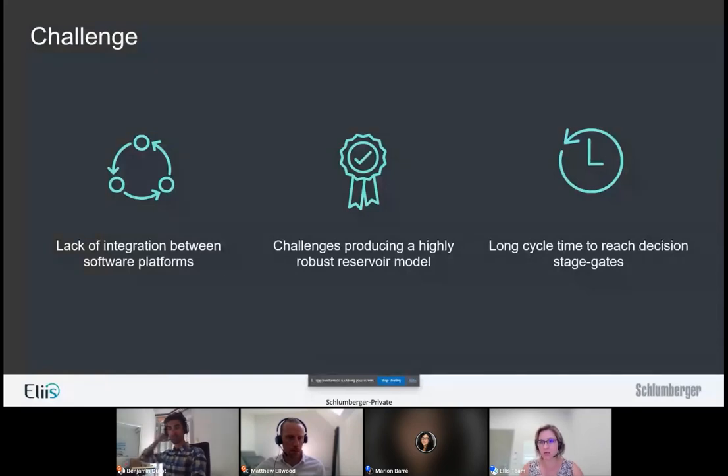Hi, Benjamin. Can we create a horizon stack from the model grid in which horizons will follow the specific polarity? Yeah, hi, Dovana. Thanks for the question. It's a good question, and it is now possible to do so. We have different ways to create the horizon stack. Usually we go through the geomodel, because it is complete throughout the entire survey. But we now have an option where we don't need to create the geomodel to create the horizon stack. Straight from the seismic, we can create a horizon stack using all the marked horizons. We first need to mark all the horizons and QC them to validate them. And once they are marked, then we can create a horizon stack with these marked horizons. So that's something doable.